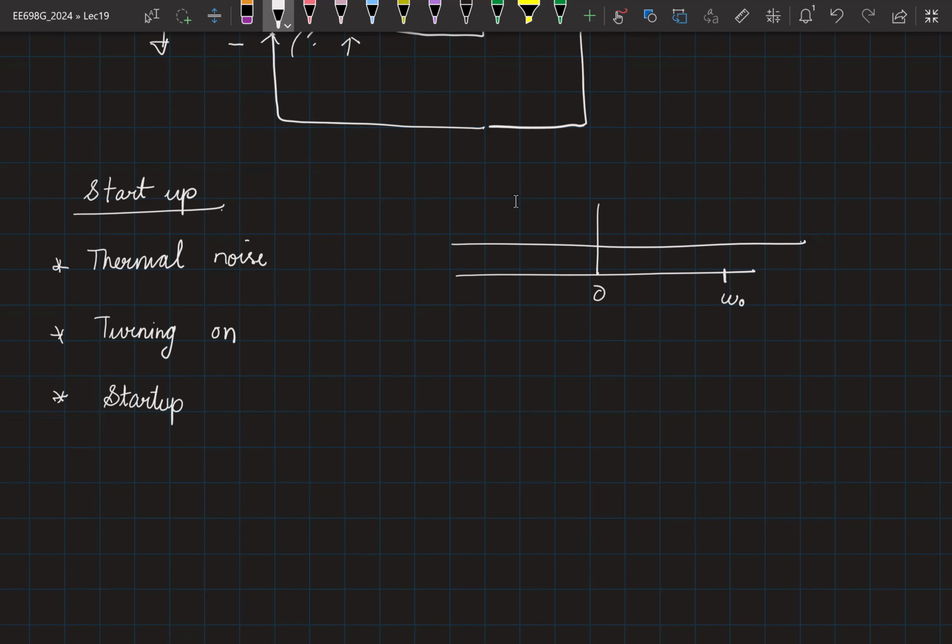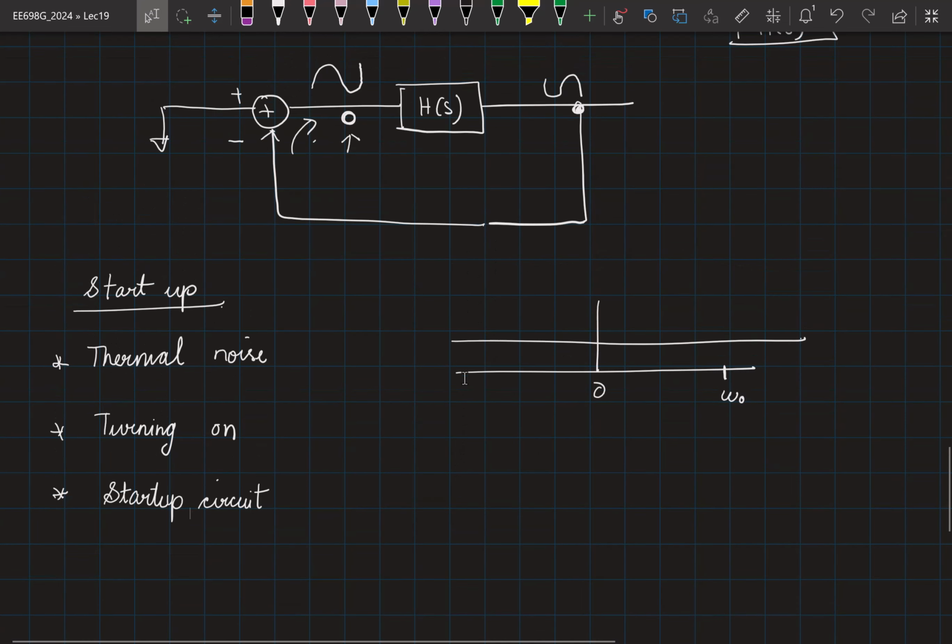Which component are we turning on specifically? We haven't taken examples of the circuit yet, right? Only once you have the implementation will this be clear. But typically, you may have a capacitor or an inductor in the circuit, and if you initialize it, think of an LC tank: if you initialize the capacitor, then provided you don't have any other resistance, it should oscillate forever, right?